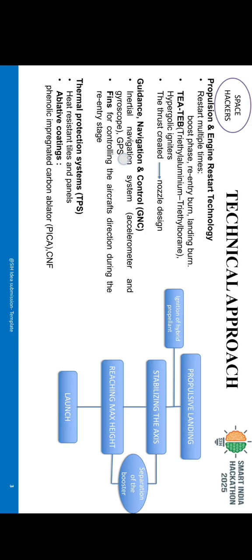Finally, for the thermal protection system, we have used heat resistant tiles and panels, and also ablative coatings like phenolic impregnated carbon ablator, PICA, and CNF. CNF stands for carbon nanofiber.